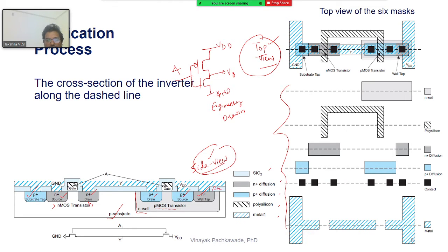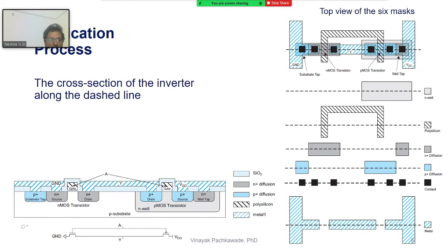This is the region I am calling a thick silicon dioxide, and it is there to avoid the metal contact connecting to, making a short circuit, and at the same time this material, thick SiO2, is helping me to isolate all these individual regions because they should not be shorted, right? So this is how I see that my side view looks here and the top view looks here. You should be very good in visualizing and understanding these two views of your layout. Okay,